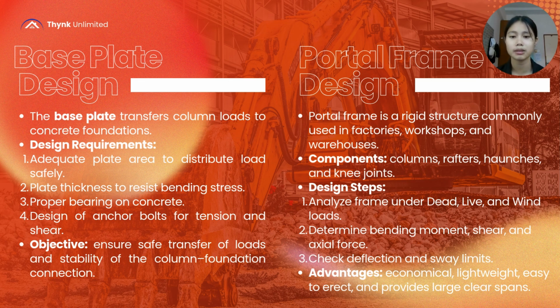Second, plate thickness to resist bending stress. Third is proper bearing on concrete. And next is design of anchor bolts for tension and shear. And the objective is to ensure safe transfer of loads and stability of the column foundation connection.